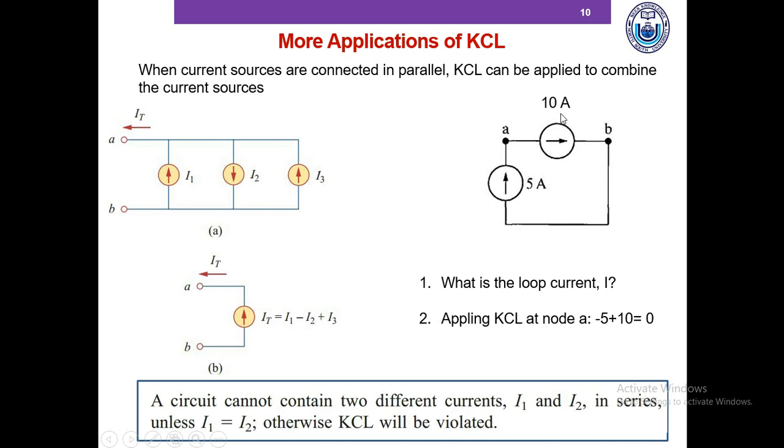So when we're trying to assess the validity of a connection, we need to see whether or not we can find voltage sources in parallel and/or current sources in series. If we don't find these two suspicious combinations, we can say that the circuit is valid.